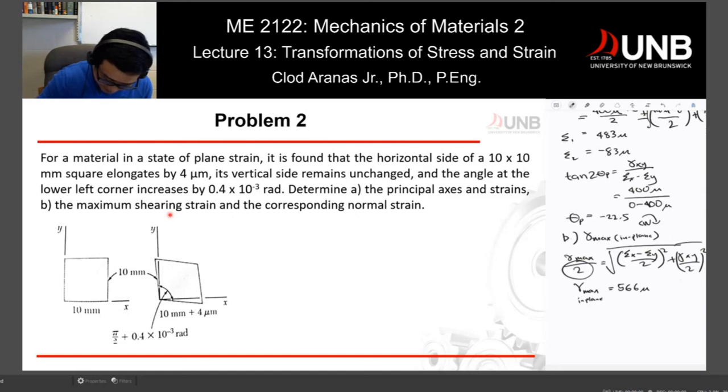Okay, how can I explain this? If you are in the maximum in plane, take note of the components. Let's go back to our shear stress, and you should please know this one. If you have the in plane maximum tau for transformation of stresses, take note that at this particular location, your sigma x is equal to sigma y.